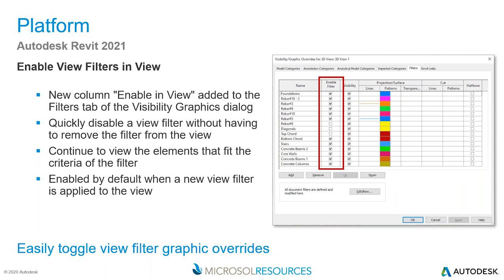So the filters, there's been all kinds of cool enhancements with the filters within Revit. View filters in the visibility graphics dialog box are view specific, and we can do all kinds of conditional statements that allow us to select and modify visibility or color or patterns based on the criteria. So there's and, or, and but conditions to create those selections.